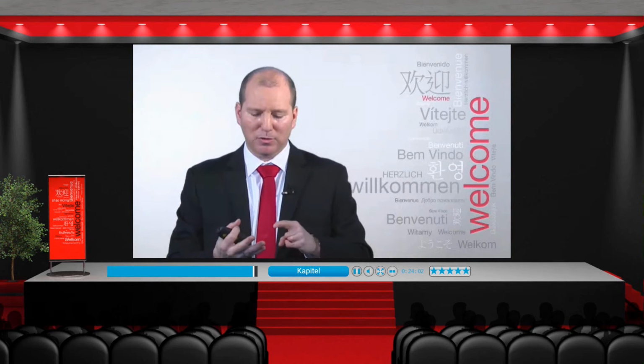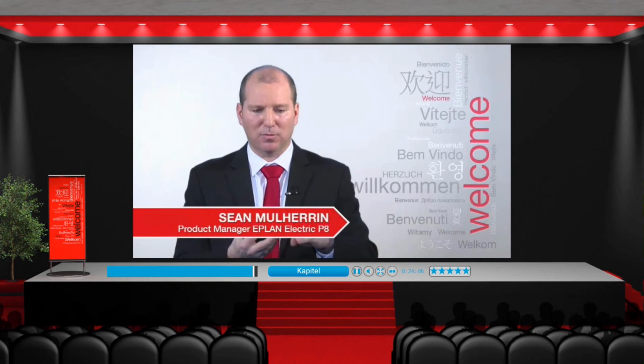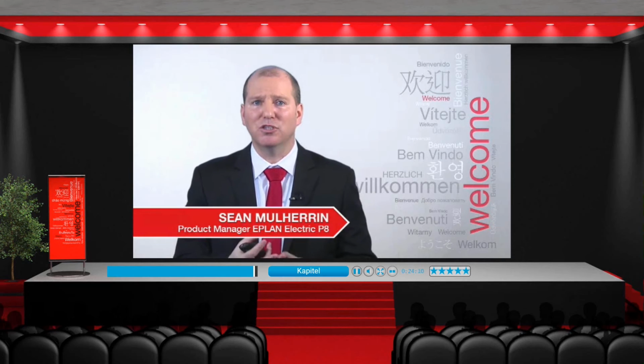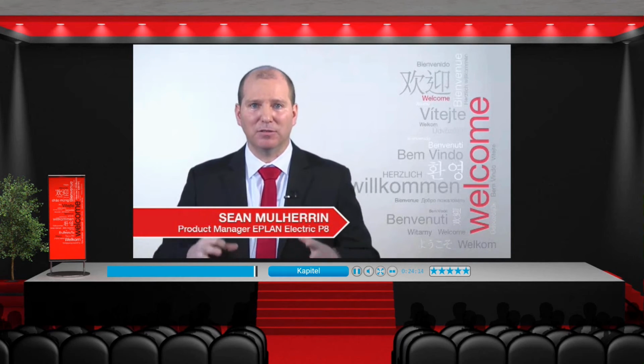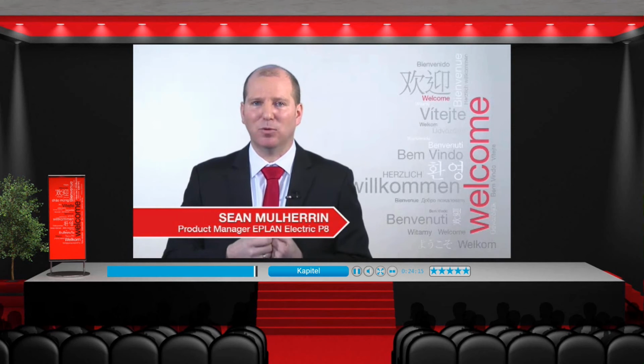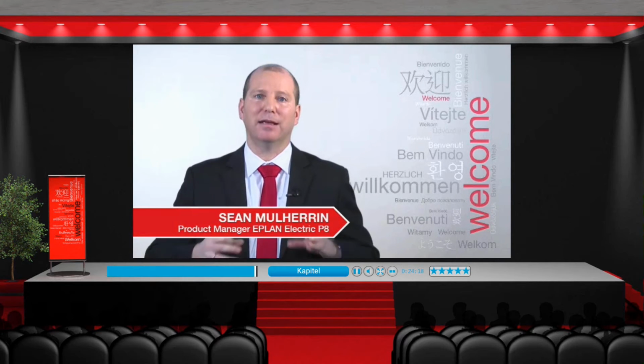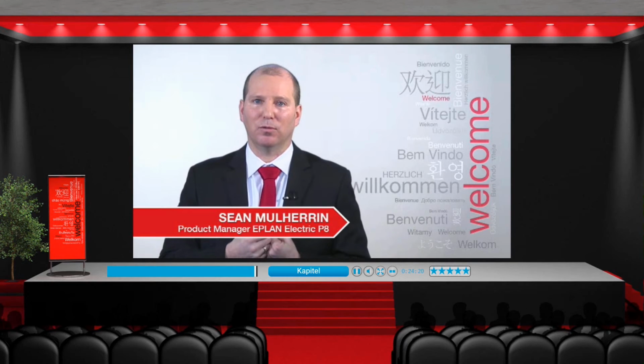What standards does the EPLAN platform support? Well, we support all of the standards. Out of the box, we provide you standards support for IEC standard. We provide standards for the NFPA, JIC standards, or even the GOST norm, or the GB norm for the Chinese market. So we already have a lot of standards in the package available, but at any point in time, you can also add and modify those standards to support your own.